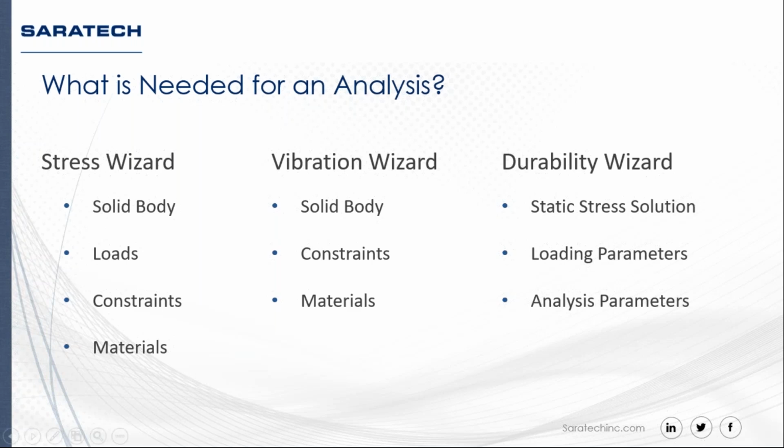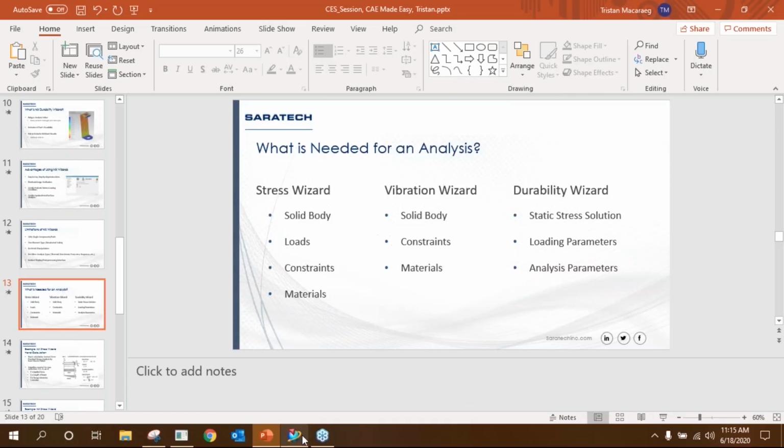And then the durability wizard is a little bit different. It requires a static stress solution, so it does require stress wizard to be run first. Then you'll give it loading and analysis parameters, where you give it options on how it should solve for your life cycles. So with that being said, I will start the demo now.